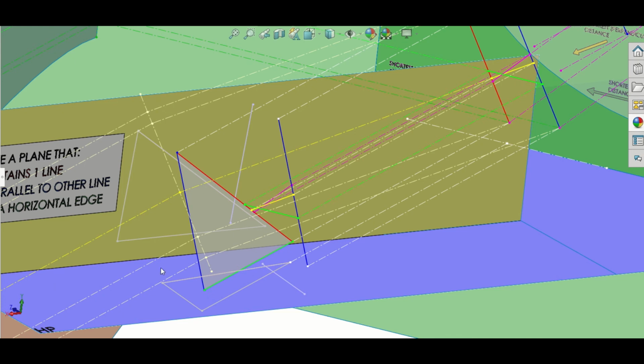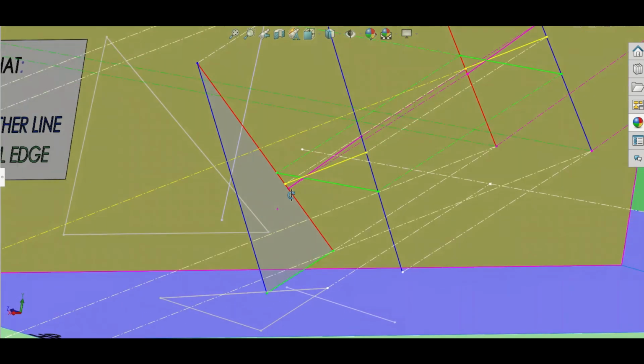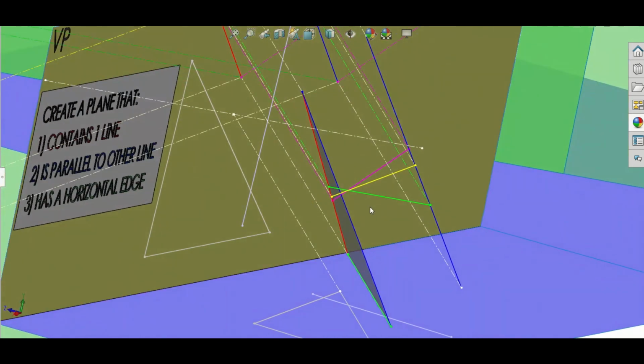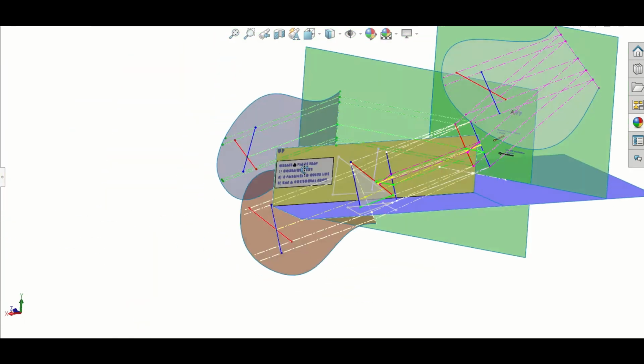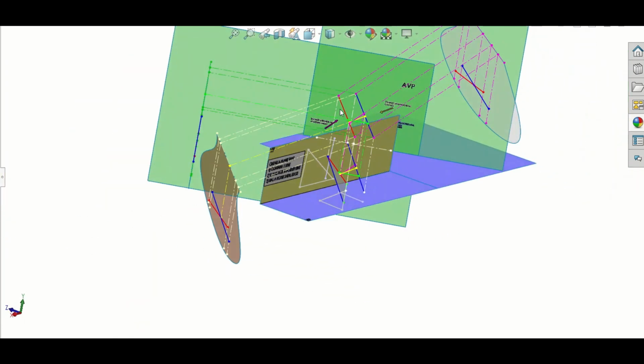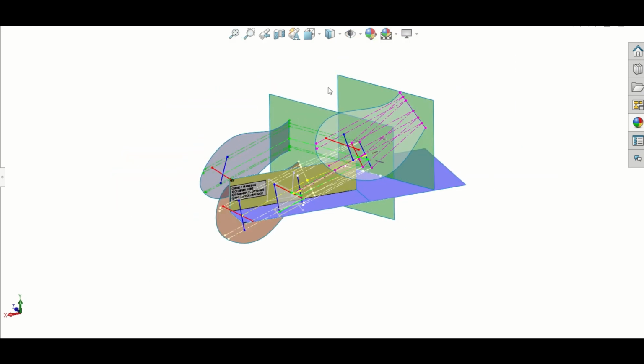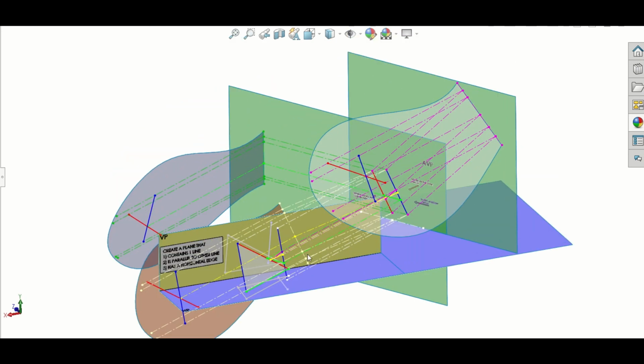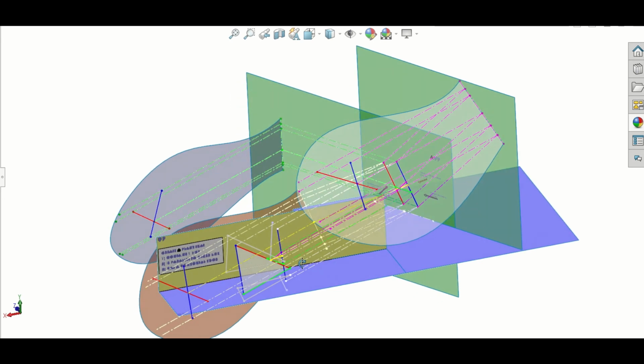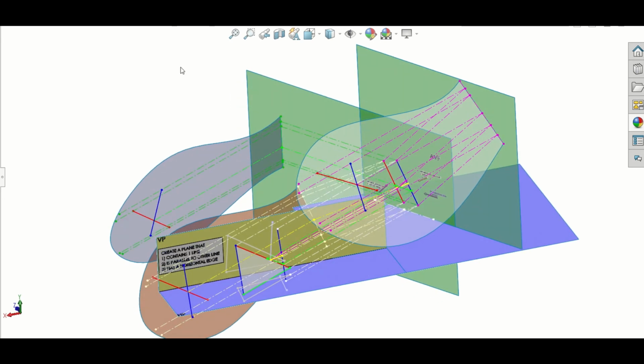It's hard to even see what's going on with it, but if it's possible at all to see it, there it is. I have my shortest distance in yellow, my shortest horizontal distance in green, and my shortest 45-degree distance in pink. There's the tree. And they all just come from different ways of viewing my parallel lines. So let's get back onto paper. Let's get this thing finished. And that is a real crash course, but a fairly comprehensive crash course, I think, in all things skew lines.